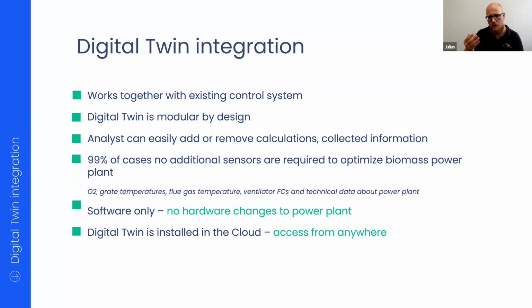And then you have the documentation once you buy the measurement device, and you go to the digital twin, push a button to add the measurement device, and specify the IP address where to look for it. Then you say that it's, for example, active power, and that it's in block 3 using Modbus protocol. All of that information would be in the documentation.